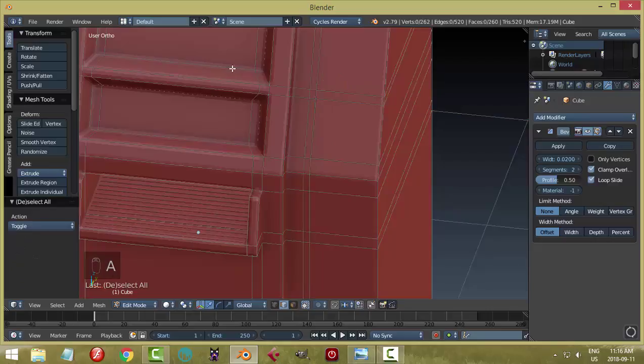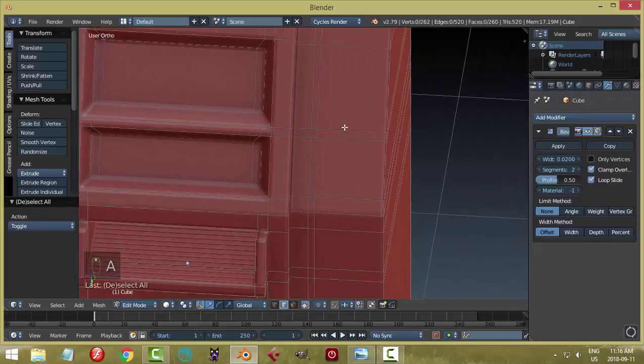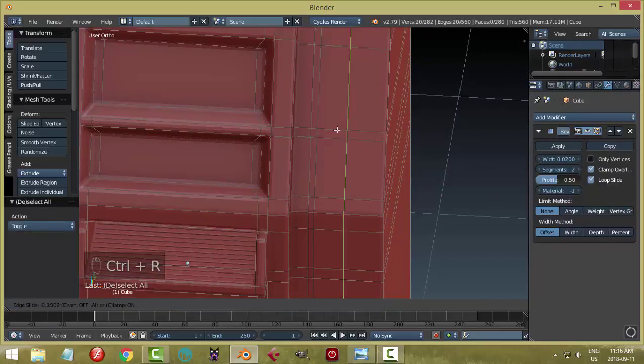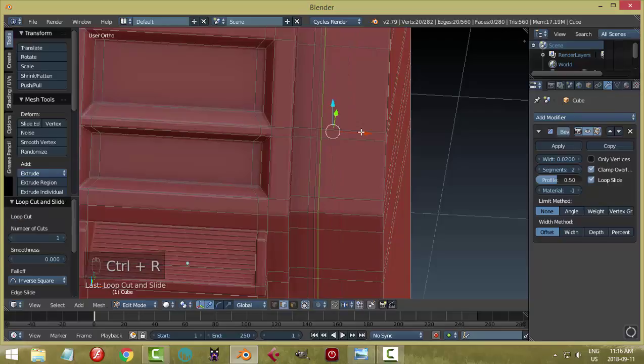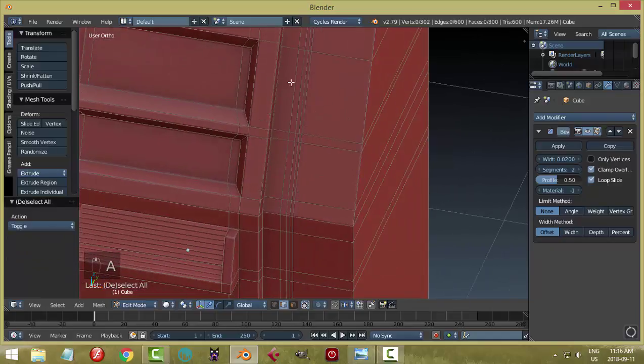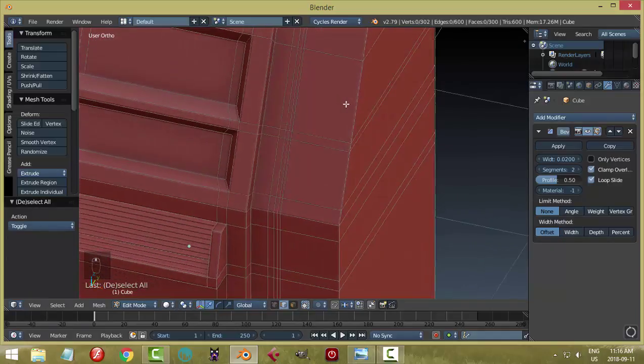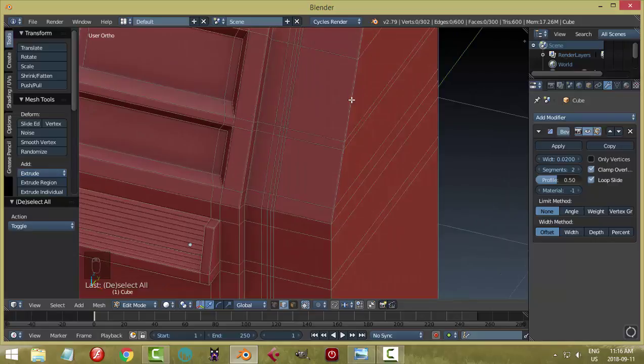Now this can affect the bevel. You see it updating in real time. Let's do another one for the hole. Nice and close by, and do one more. And this one's going to be very close. Just a thin little hole. I'm not sure I want it that tall though, so I think I will put in another couple of edge loops.